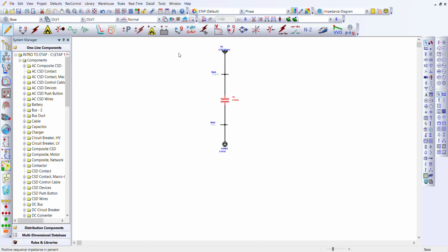Now, when we go to impedance, percent impedance, let's use about 6% impedance. Then the X/R ratio of the transformer should be, let's say, 17. I think that should be all for this for now. Then bus 2 rating for the nominal kV, let's use 4.16. Now let's go back to this transformer. See, bus 2 is currently 4.16. So we're on the right track.